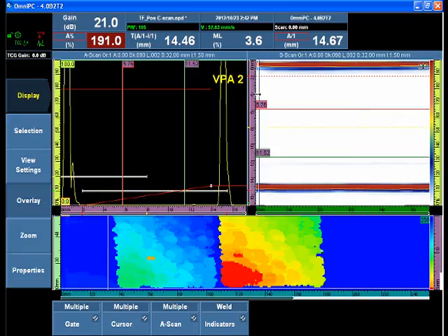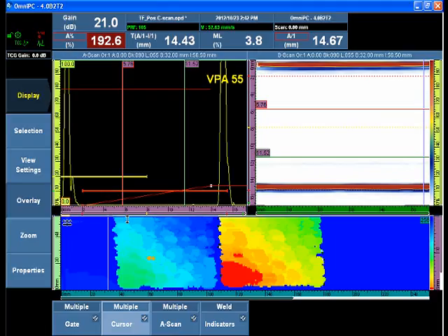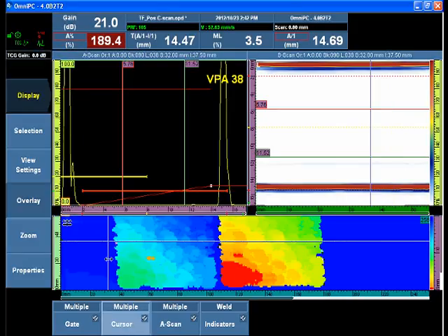On this side of the probe, we see the A scan generated by elements 1 through 4. And on the other side of the probe, we see the last focal law generated by elements 57 to 60. So as I move the probe or scroll through the data on the scan axis, we'll first see the bottom of the component, or the back wall, and we can see that gate A has been placed over the area of interest to include the back wall.